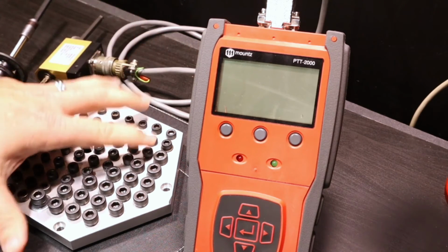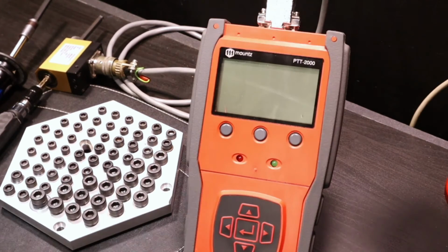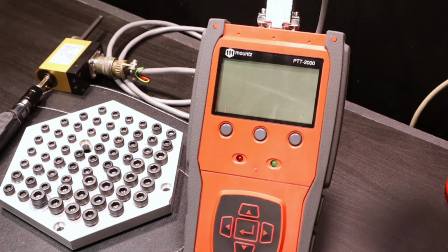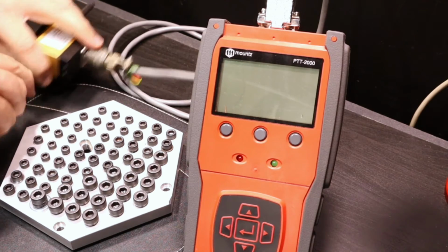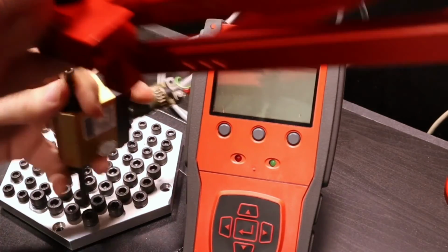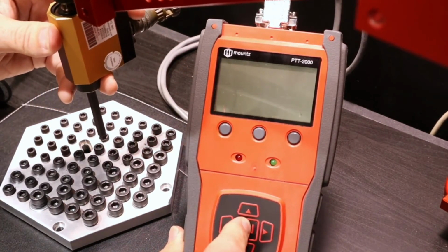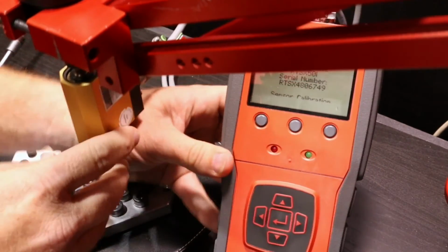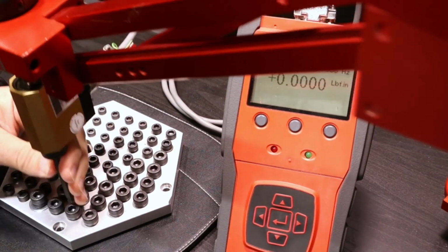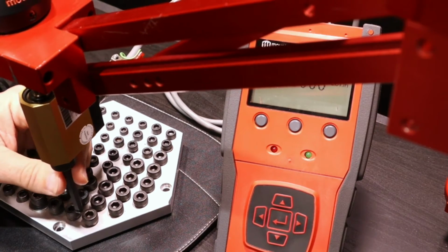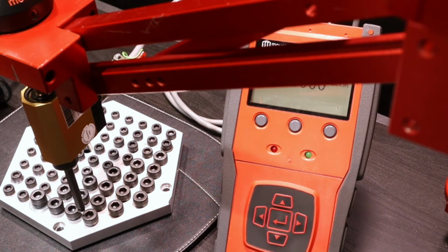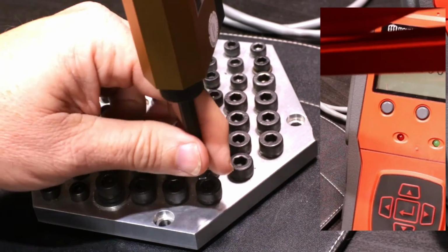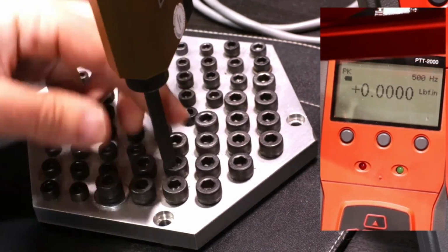I also have a torque screwdriver, and we'll go ahead and run some fasteners down. We'll do the different tests just to show you how those different tests function. So let's go ahead and run some fasteners down first. Power this on, and if we set our preset here to 1, we can go ahead and run these fasteners down to about 18 inch-pounds or so on these first 4. And let's move this here so you can see that a little bit better. And so I have the rotary sensor hooked up to our analyzer, and then we'll go ahead and run these fasteners down.